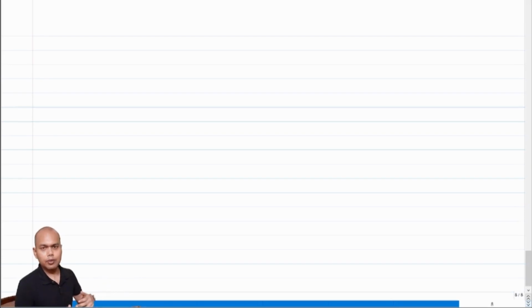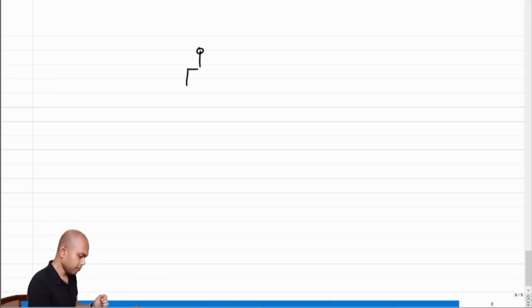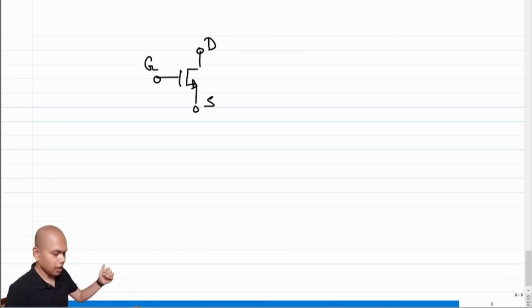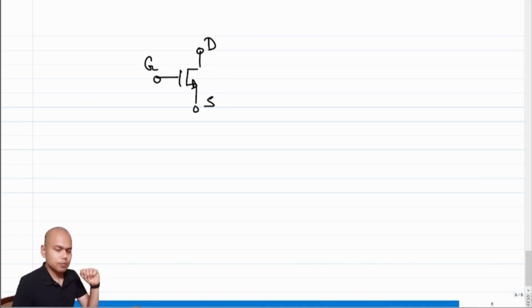So what do you think will be our architecture from the perspective of looking into the impedances, right? So a MOS transistor has, as we know it, three terminals, right? We have gate, drain, and source. Among these three terminals, only two terminals can take in a current input. The current cannot go into the gate, so there's no point in considering that as one of the input terminals for a current controlled current source, right? So which terminal can be used?